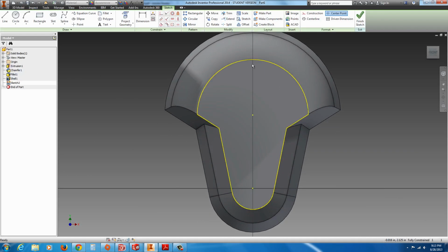Now we're going to put one of the little petals in the middle here, so we could first go to line and centerline, and just at the bottom there drag up a nice centerline, escape, turn off centerline, and now we could go to the line tool and proceed with a very similar method we did earlier. We just draw a line over here, a slight angle. Now we could go to mirror, and we need to select the angled line, hit mirror line, and select the center line. Hit apply, and done.